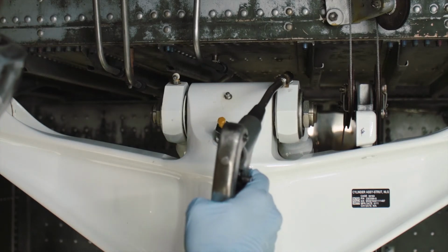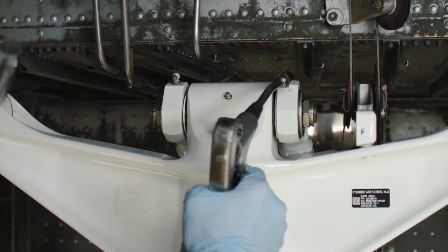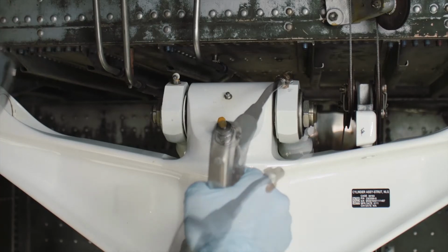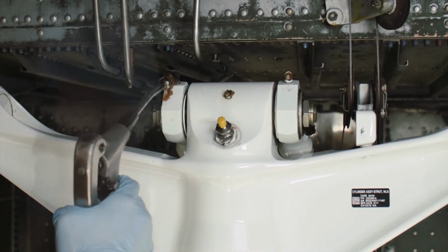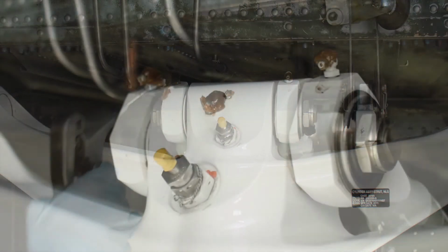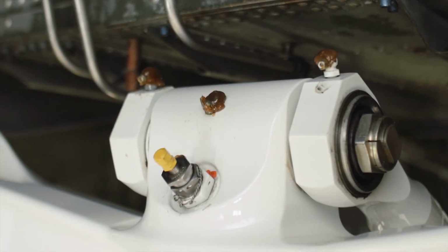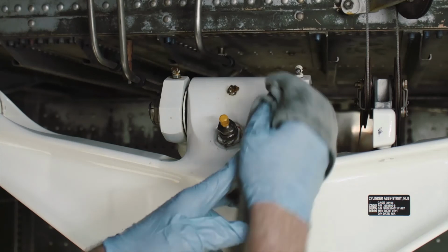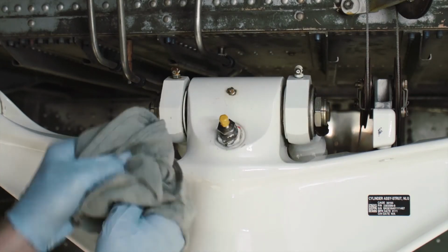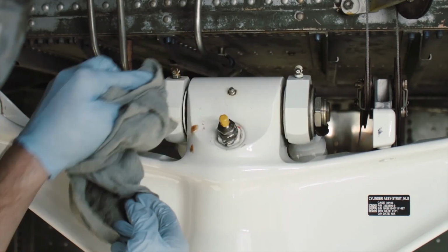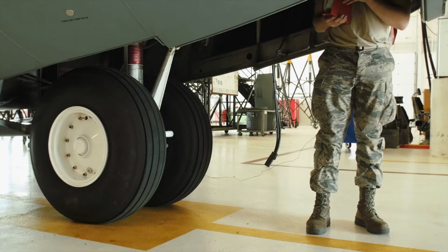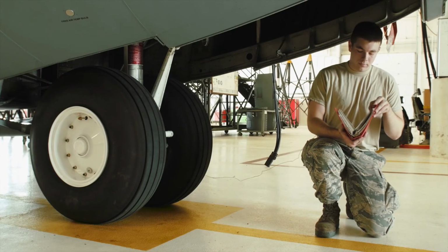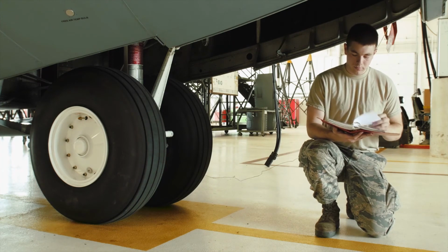After you complete the cleaning process, you must reapply lubricants and grease to required components. This is important to prevent material wear and moisture accumulation and to fill air spaces in order to restore the basic barrier against corrosion. Be sure to remove any excess grease around fittings or excess lubrication on hinge assemblies to prevent the buildup of dirt, moisture, and debris. Always refer to the applicable technical data to be sure you haven't missed anything in this process.